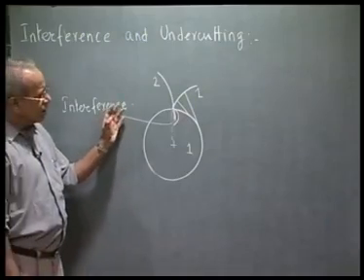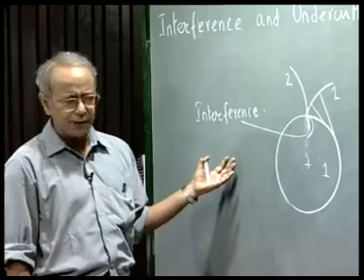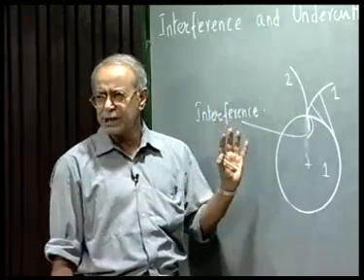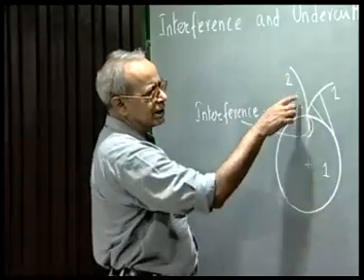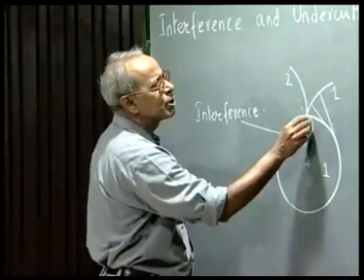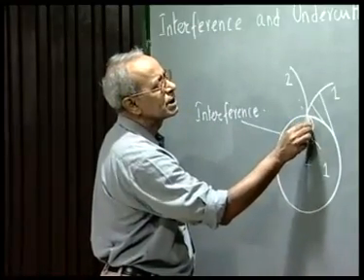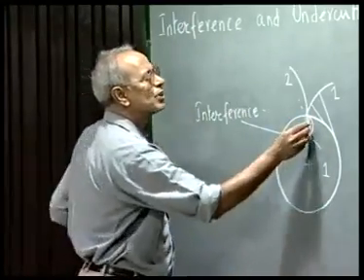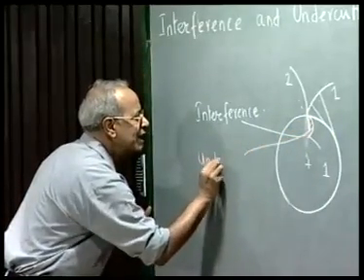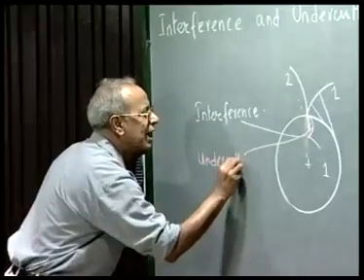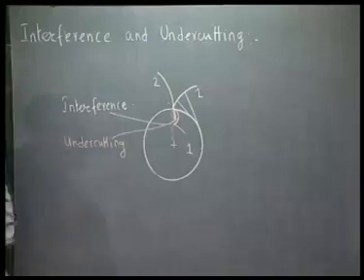However, the conjugate action may be taken care of by the other pair of teeth in engagement. So the continuous motion is transmitted maintaining the constant angular velocity ratio, but this tooth is not transmitting any power because this is getting into this portion. And this is what is called undercutting. We have avoided the interference by undercutting the tooth of gear 1 inside the base circle.